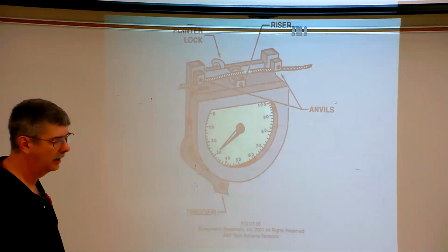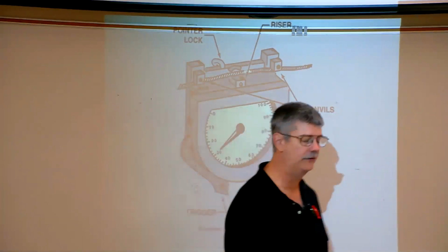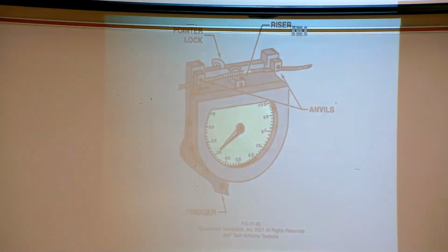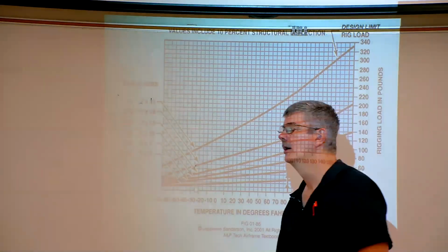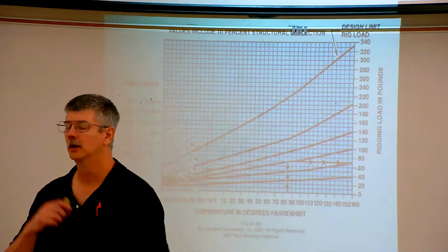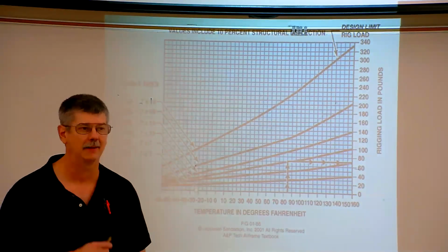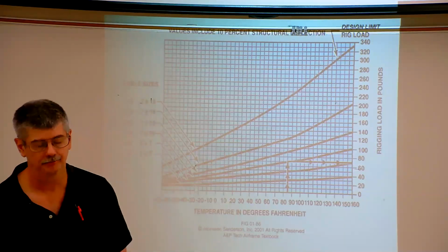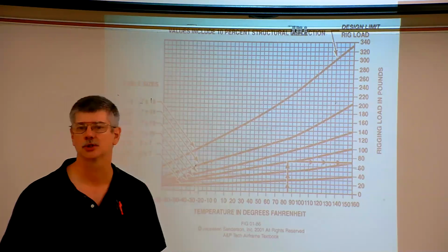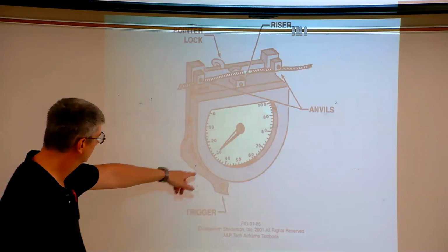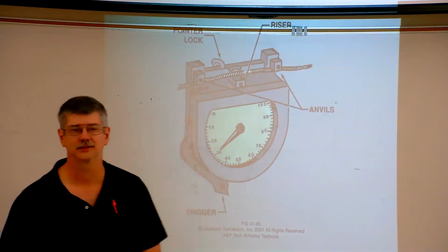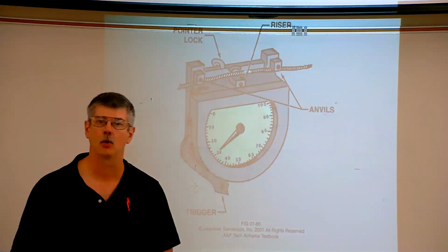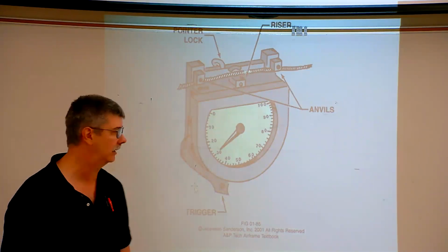We always follow the manufacturer's recommendations when we're rigging, with the use of a cable tensiometer. And keep in mind, always when you're using the cable tensiometer, check to see if it has been recently calibrated, and always follow the calibration chart, because what we see here, kind of 30, does not always necessarily mean that we got 30 inch-pounds. It could mean lower or higher than that number, so we have to follow the calibration chart.